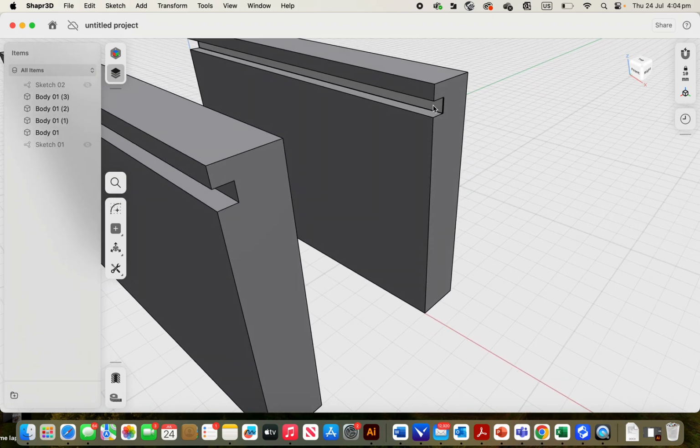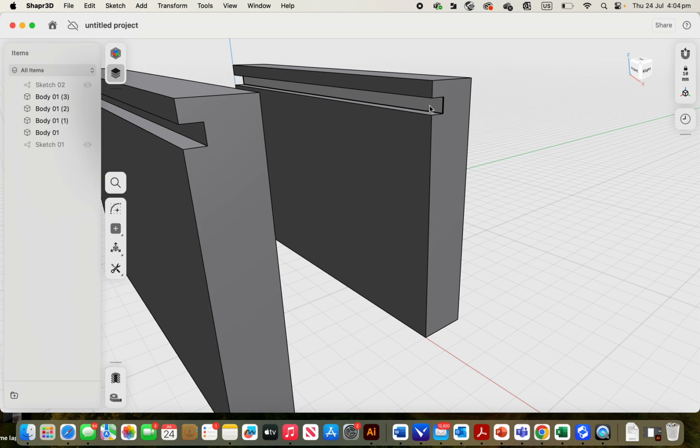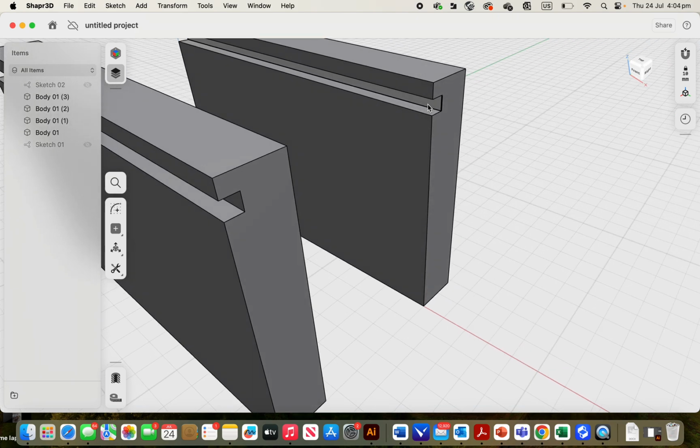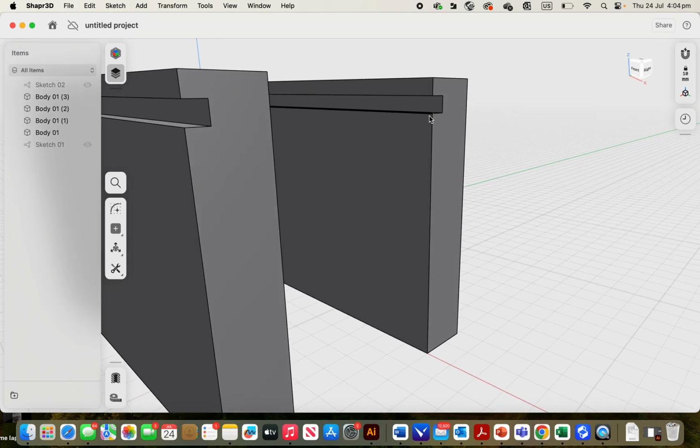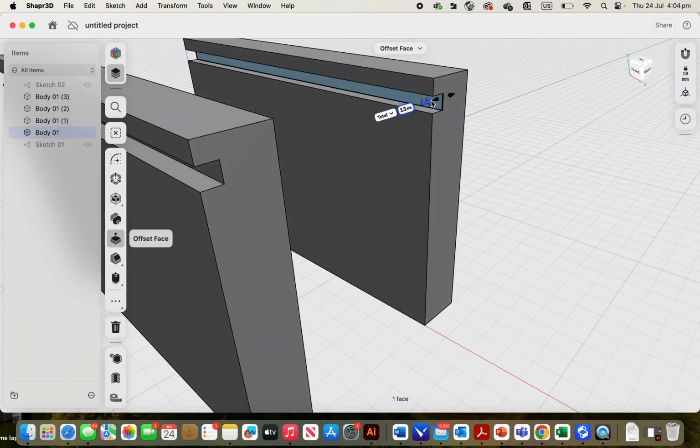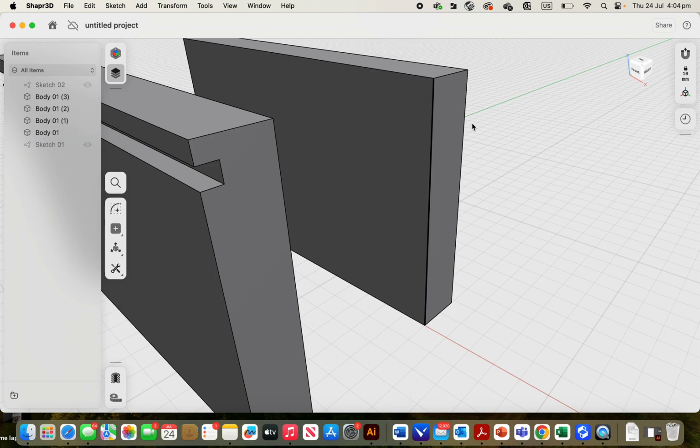You can see that's a groove in there. Put it on the inner face of the groove there. So we're not looking to touch on this face or the top one, but the inner face. Click on that there. It says currently 13. What that's telling you is that from this line to this line is 13 millimeters. To get rid of that groove on this one piece, we need to change that to 18. So what we need to do is type 18, and that groove's gone.